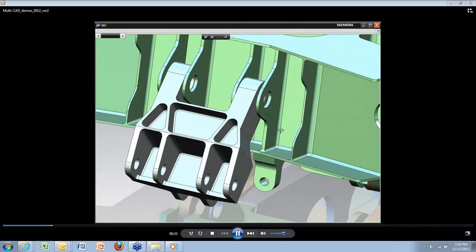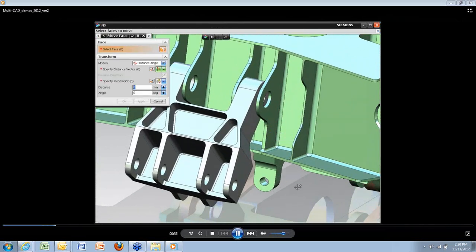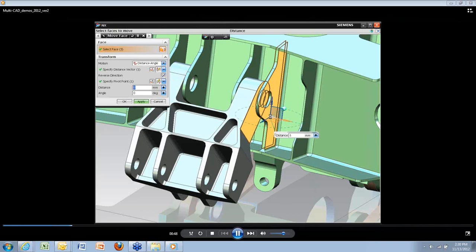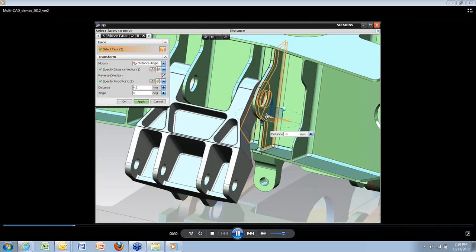Now we will change the thickness of the swing arm and the positioning of its mounting ribs. Using Face Finder, we can pick one side of the rib and the offset option will automatically select the other side. Then we pick the corresponding face from the other component.